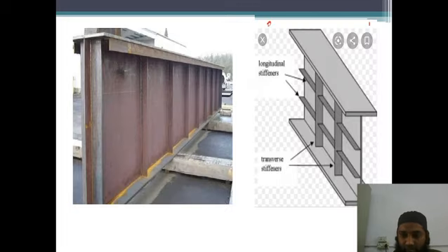You can see here the vertical stiffener which is provided at the ends, that is called an end bearing stiffener. As there are chances, because of loads, of the web buckling away, the same situation can happen with the flange also, buckling in a horizontal direction. So, to overcome this, we provide an end bearing stiffener which is placed at the corner.